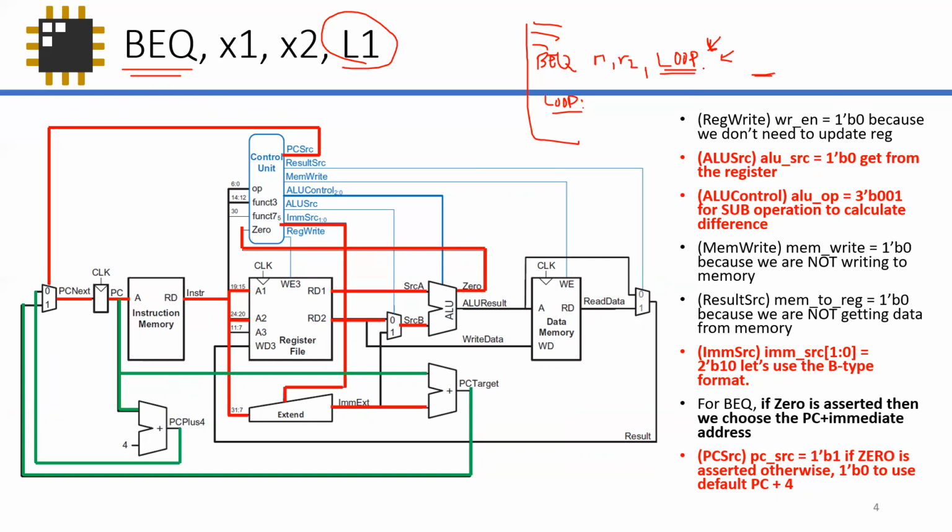Apparently, the linker or the assembler has this algorithm inside already that, okay, I know I have to jump to this instruction. Let's say, for example, the loop says I'm going to do an addi next, and let's say it's at address 52. So the linker or the assembler is gonna calculate it: I'm at address, let's say 40, and then the loop is at address 52. The linker is gonna calculate this and put that there. But we're not doing that.